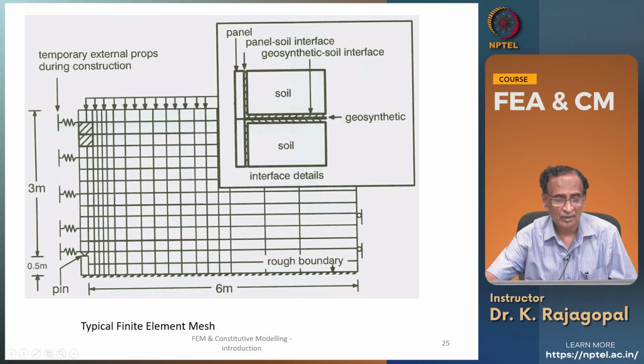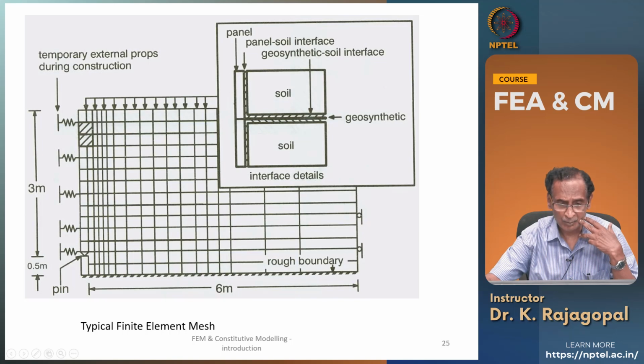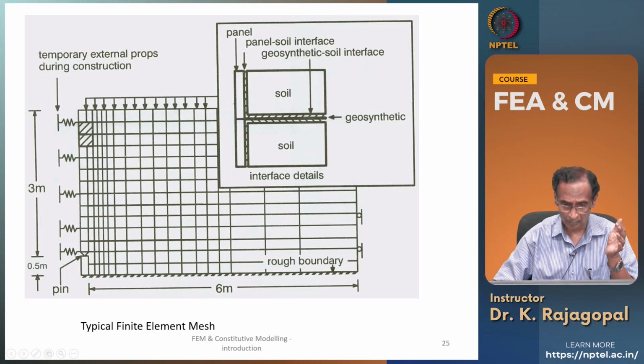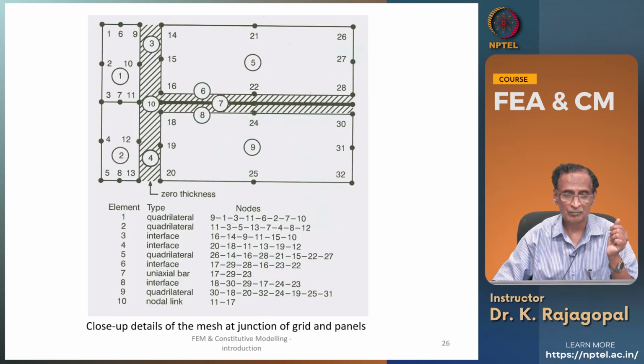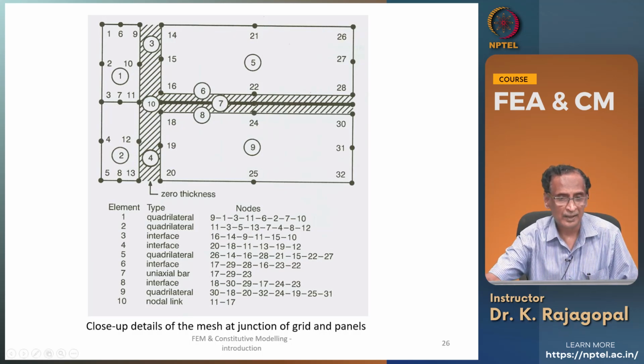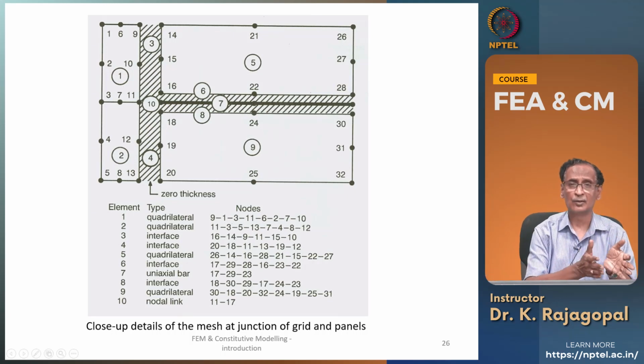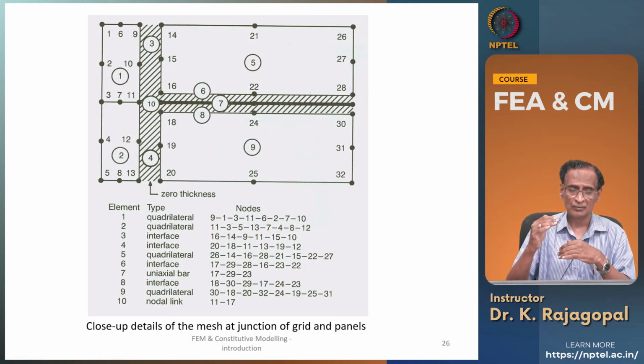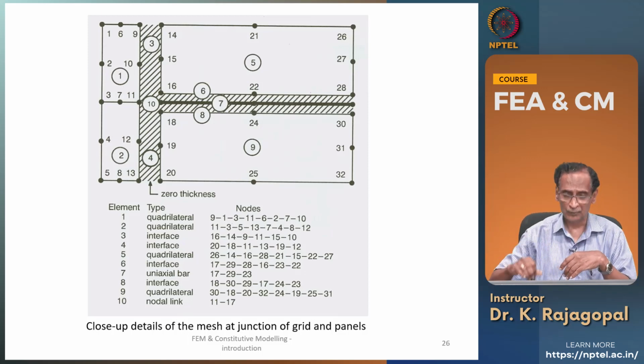Then external pressure was applied for failing them, and this is the finite element model for simulating the response of this retaining wall. And this is a close-up of the facing panel, then the soil, the reinforcement, and the interface between the different materials like the wall panel, the soil, and the reinforcement, and so on.